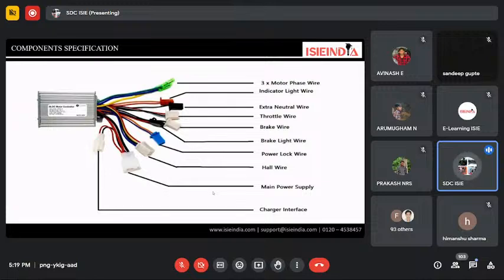Second one is the indicator light wire. Like when we start the vehicle, it indicates a green color, neutral position. So that indicator connection wire is also there. Extra neutral wire: wherever we connect the circuit, we always connect the negative to the common and the ground connection. So for any auxiliary requirement, it can be used.